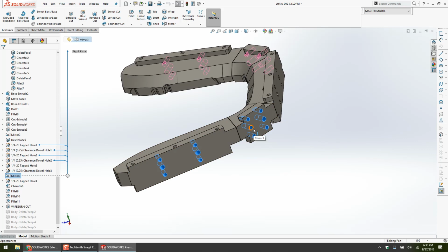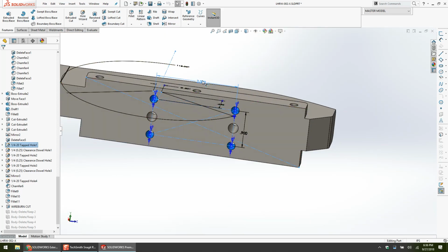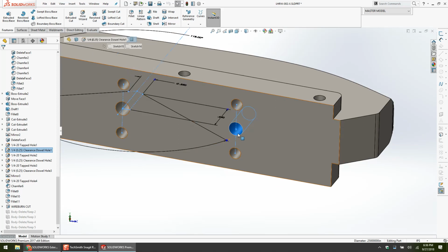But the convenient thing in this particular instance is I wouldn't have used an external reference because my slide is very stable, right? I knew the slide, I knew the profile, I knew this stuff. Within a statistical chance of never, the slide wasn't going to change. And so in this instance, because it was all a dedicated assembly and I only had to do one side and mirror it over, I just punched it out by hand, put in a couple dimensions. So I've got two dimensions, and these are natively in the middle. So this isn't dimensioned because it's just in the middle of a line that's midpointed.